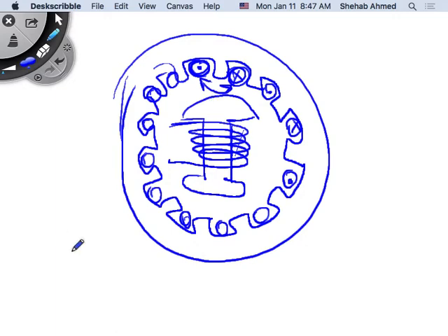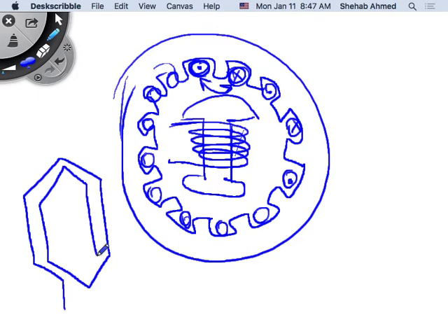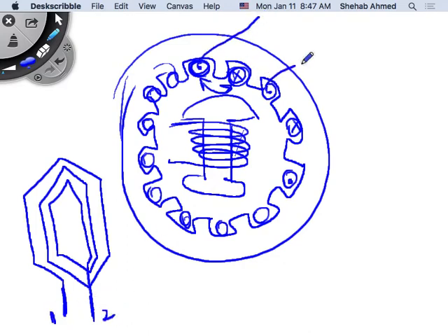And these windings are typically actually coils. So you would typically wind it like this, for example, and this would be one terminal, this would be another terminal of the winding. There are lots of these wound, and then you take this coil side and this coil side and put them in a slot here, and put this one in a slot here. So these are right next to each other. They have to be insulated. You cannot put them next to each other if they're not insulated.